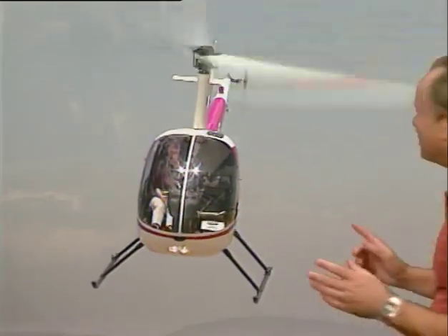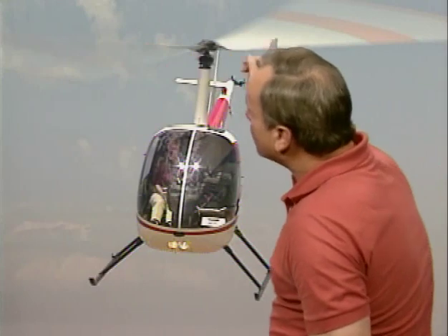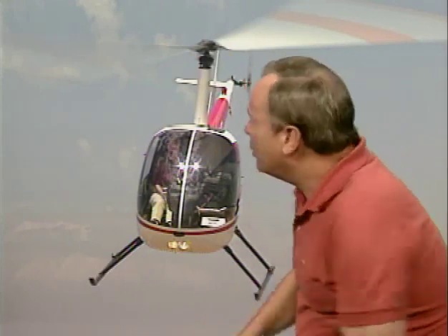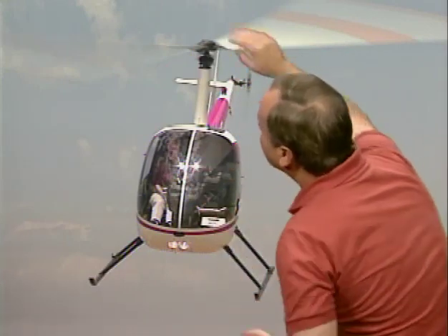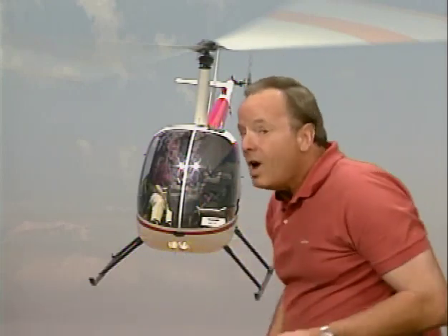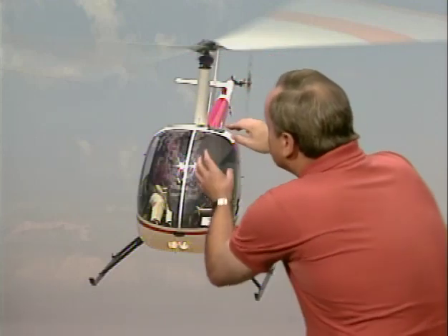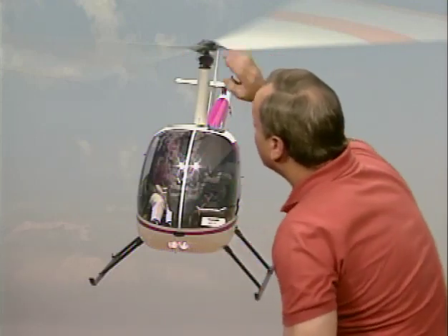Now, let's take a look at a couple of helicopter components they want you as a mechanic to know about. As you know, the way a helicopter works is the engine is driving this main rotor up here. So it is a very good idea to have the engine connected to the main rotor. But if that engine should quit or slow down so that it's no longer driving the main rotor, it's not such a good idea to have the main rotor connected to the engine, because the engine is now slowing down the main rotor.